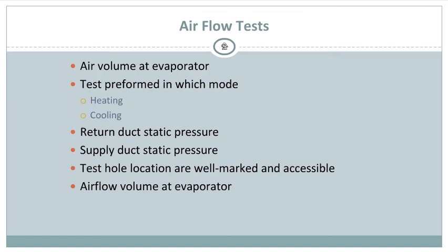It'll tell you the airflow through there, and it'll tell you the static pressure that you've got going through there. Again, depending on the static pressure in your duct system, that is going to determine the size of filter and the type of filter you need to put into your heating system. You might have to put in a type of filter. I forget what it is. I think it's a V6 or an MERV 6 filter.